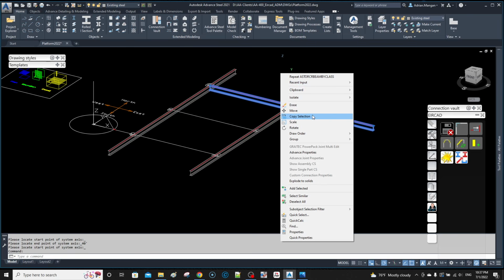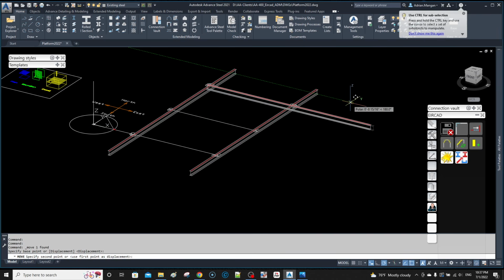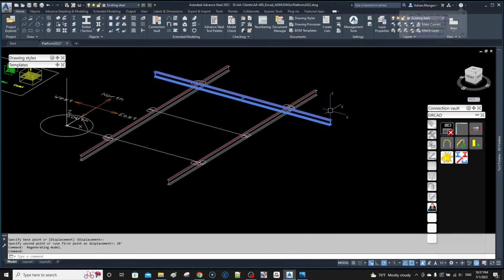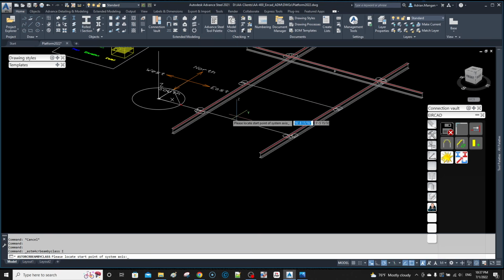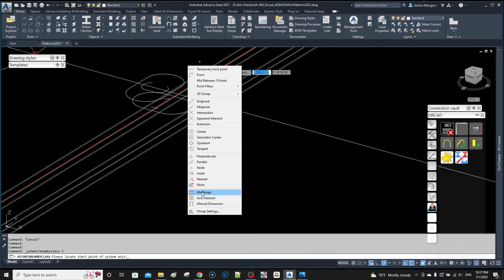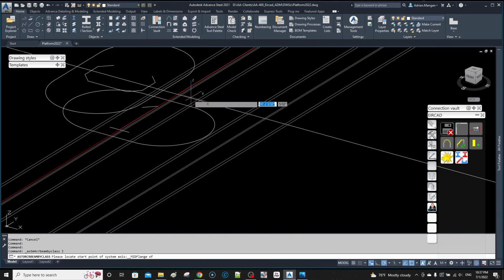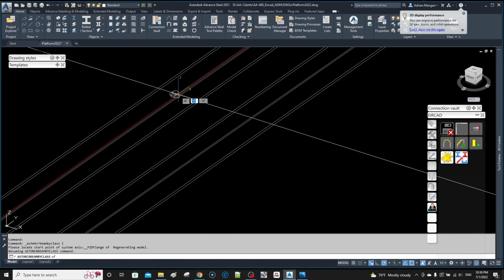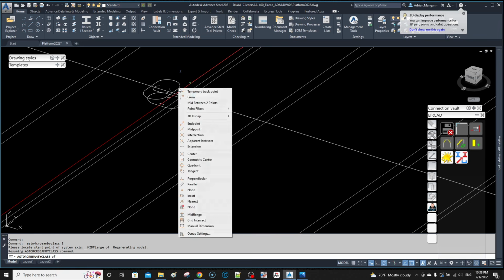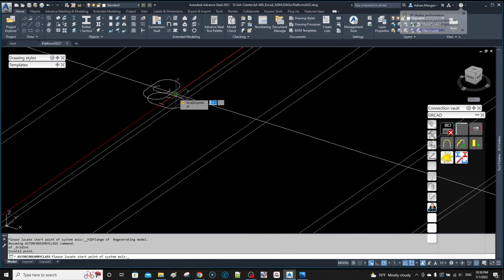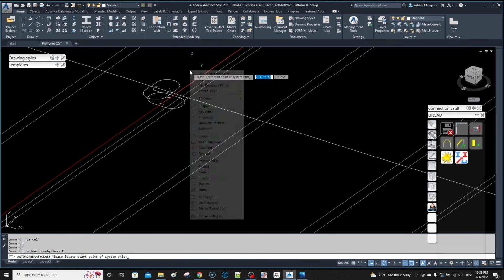So I'm going to move this back 10 feet again. Okay. So what else you can do is if you leave this on the standard layer and you draw in the beam here instead, and you go to grid intersection again, sorry, it's not snapping to that for some reason.